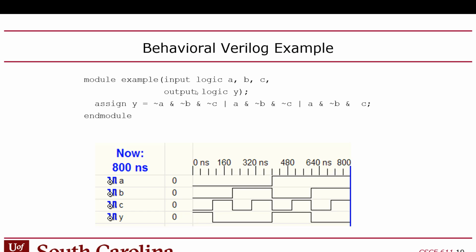Usually when you simulate these, you have a vertical cursor, shown in blue here. You put this vertical cursor somewhere on the timeline, and then these values here will show whatever is under the cursor. When you debug these, usually you just put your cursor somewhere and read the corresponding value. So it looks like a logic analyzer, or an oscilloscope, essentially. You could also have it display every triggering event as just a line of text or a row, but the waveforms are, in my experience, the more common way of simulating these things.